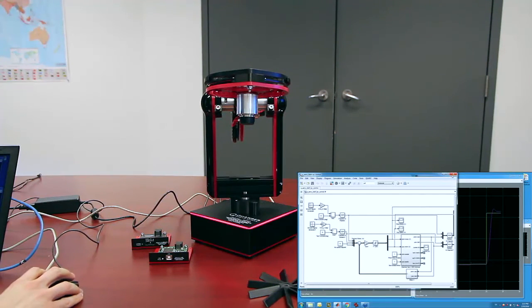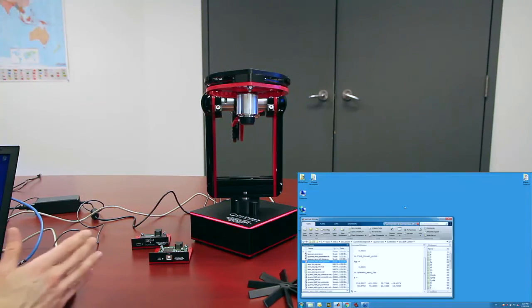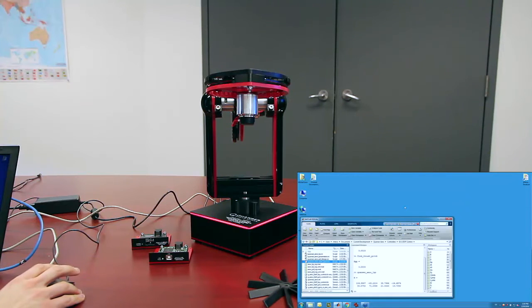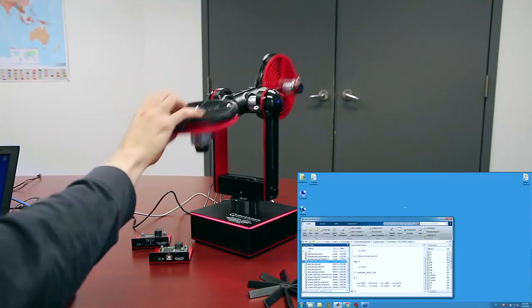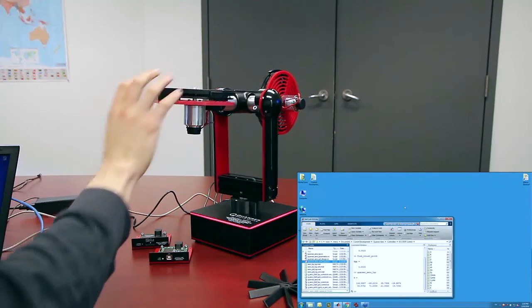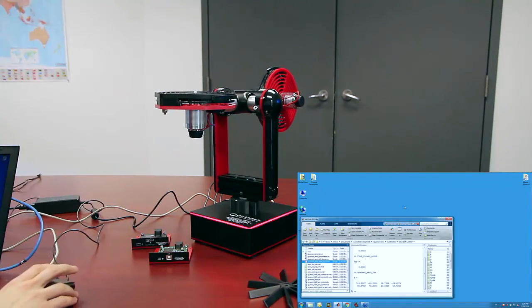I'm just going to go ahead and stop that. And again, you can save all this data, and of course, everything is totally open, so you can change around your controller. So for this one, besides parameter estimation, which I've shown you, and controlling, you can also do observer design using the IMU for attitude estimation of the pitch and yaw. So there's a number of different things that you can do that you can progress from what we've supplied.